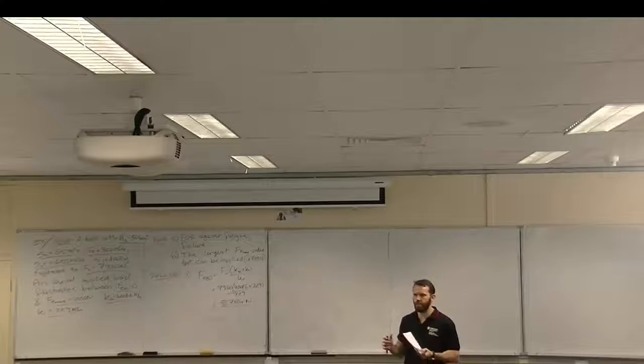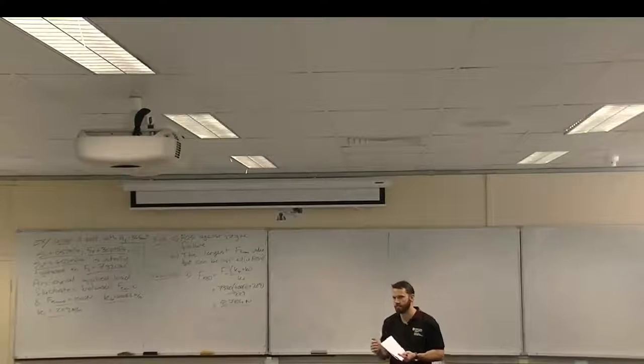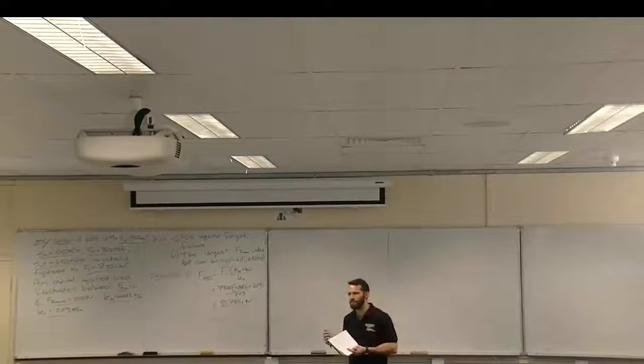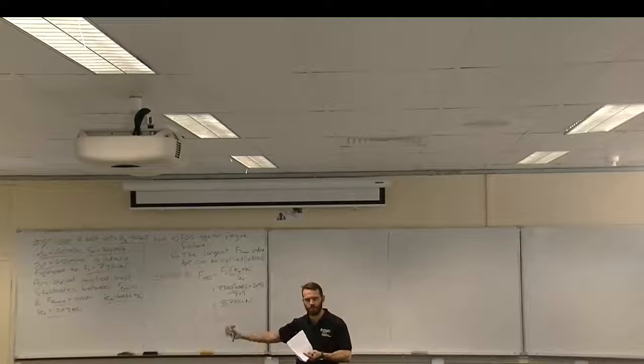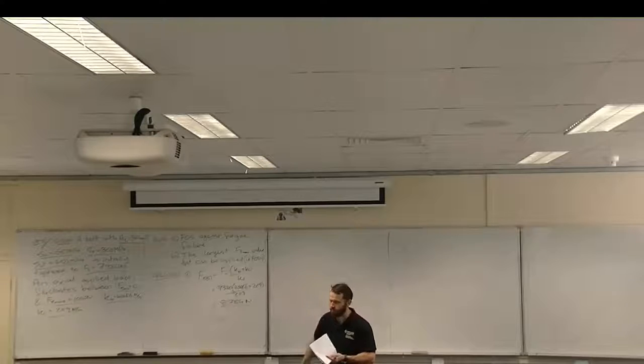Alright, so are we to the left or the right of separation with our loading? Under? Yeah, we're under by quite a lot. In terms of separation, where are we at in terms of factor of safety or overload factor? Yeah, 8.7. Going on 9. So we could increase by a factor of 8 before we actually got separation. Now that says nothing about bolt strength or capacity, but in terms of overload and the factor of safety against separation, we're 8.7.